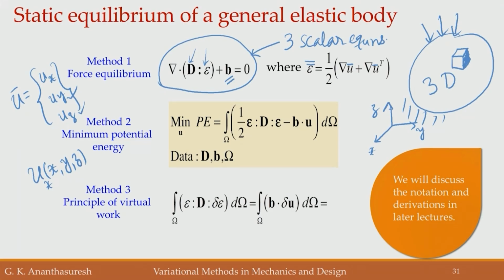In order to solve for the 3 unknown functions ux, uy, uz, you need 3 equations, which are over here. That comes from the force equilibrium. If you take a small cube and do the force equilibrium, that is what you get, and the strain is given by this expression for linear small strain, but the same holds if you have a non-linear strain here. You can get a force equilibrium which will look like this, with small changes in the stress and strain, corresponding to the stress that you need to define.